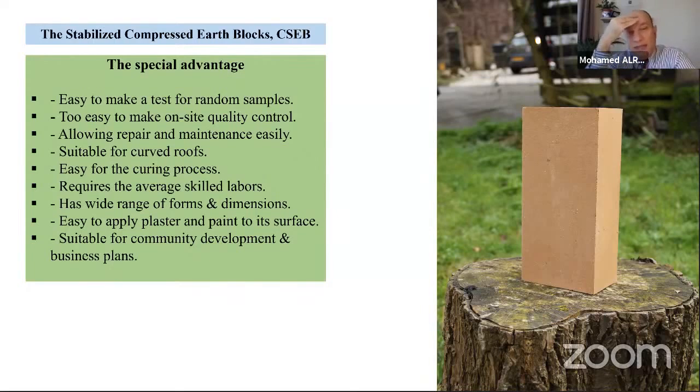And it is very suitable for curved roofs, because here again you are dealing with just a block. And it's easy for the curing process. Again, you can stack all these blocks into groups, maybe 200 or 300, and cover them with simple plastic sheets. You can reuse these plastic sheets over and over again, and it requires average skilled labor.